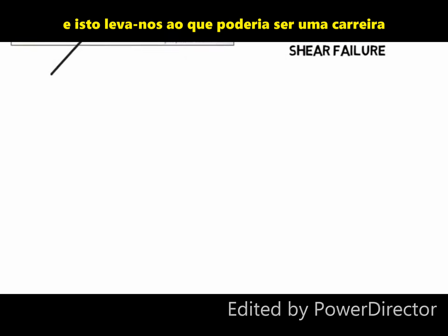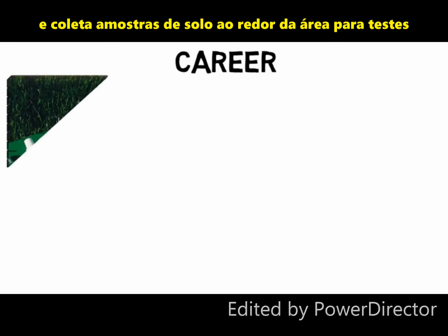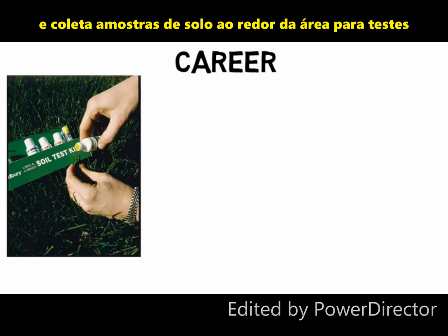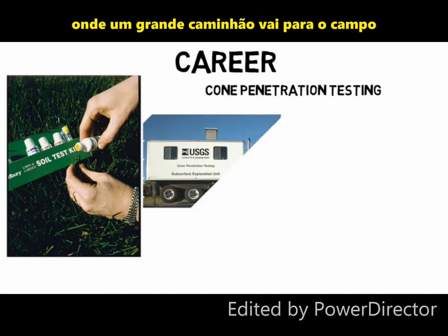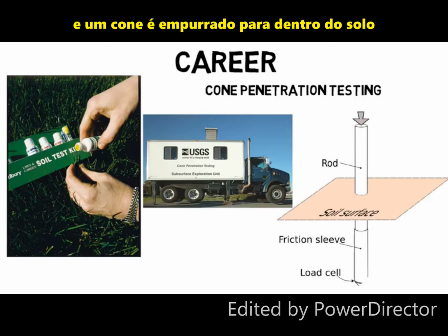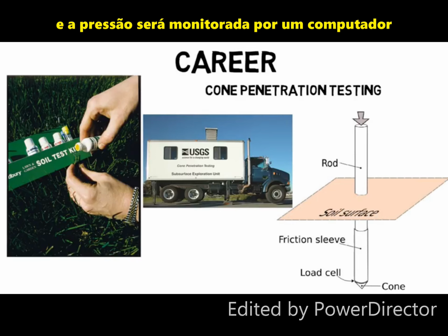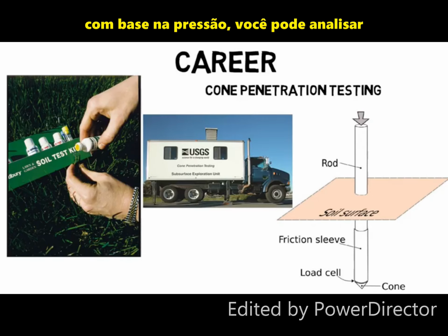And this leads us to what a career in geotechnical engineering could be like. You might be the person who goes out to the field where a structure is going to be built and collects soil samples all around the area for testing. Or you could do testing at the field. One of the most used tests right now in this field is cone penetration testing, where a large truck goes out to the field which has all this equipment on it, and a cone is pushed into the soil, and the pressure will be monitored by a computer on the truck as it moves through the soil into the earth. Based on the pressure, you can analyze the soil mechanical properties.